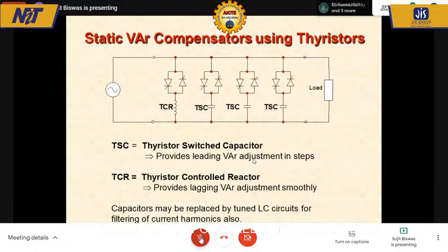We talk a lot about HVDC supplies, high voltage DC supplies, and each HVDC station still comprises phase control rectifiers. So you have to appreciate that every phase control rectifier used in HVDC stations will be generating harmonics and VAR.